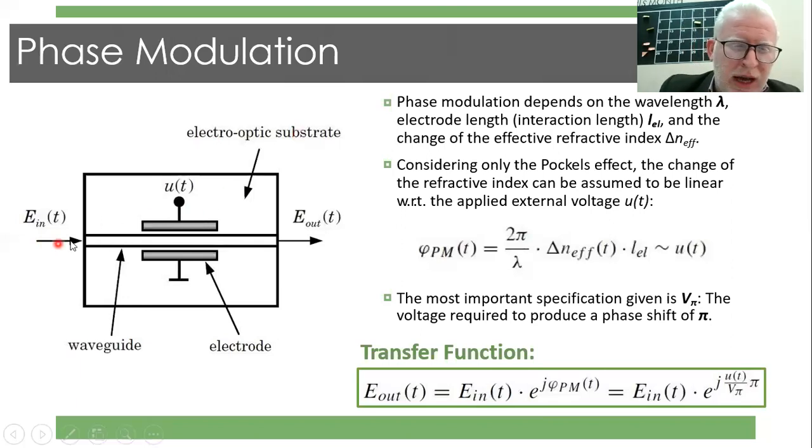So whenever the wave propagates, there is a change in the phase, and this change in the phase is equal to e^(-jk times the distance), where k is the propagation coefficient, and if you remember, k equals 2 pi over lambda. So this is typically what you do with the waveguides in the microwave, assuming there is no attenuation coefficient and there is only a variation in the phase while the signal is propagating. And you can easily agree with this